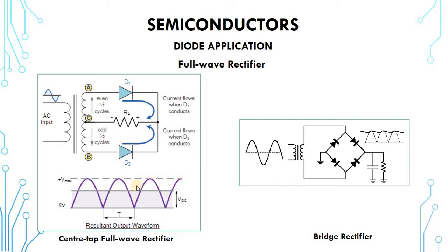So at the end of the day, the load does not see the current going to 0, because as the current from the rectifier is dropping to 0, the capacitor discharges to the load. So the waveform that we are going to see by using the capacitor here will be something like this. Instead of this that we saw initially, now the current will be like this.